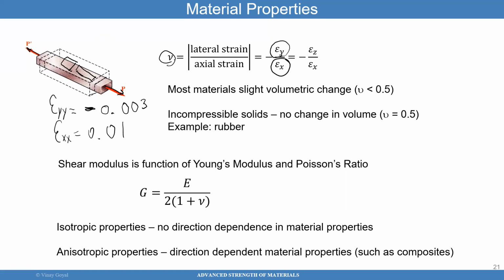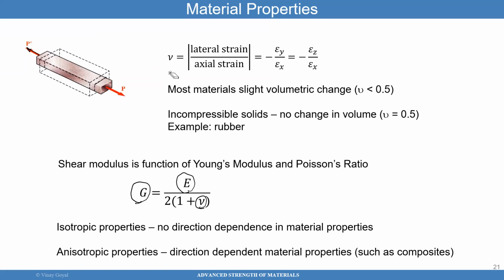It turns out that the shear modulus, incredibly, is related to the Young modulus through the Poisson ratio. So I can do a test. Let me show you this. It's incredible. I can do the very test you see in the top left. If I apply load P, I can calculate sigma XX: that's P divided by the initial area. We also learned that I can calculate the strain from the current length minus the initial length, divided by the initial length. So I can plot this against that.